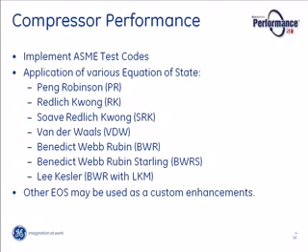In addition, we apply various equations of state, some of which you can see on the screen, and the proper application and configuration of these equations of state is based on the operating condition and also the fluid types that go through the process compressors.